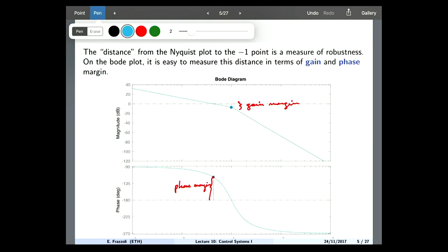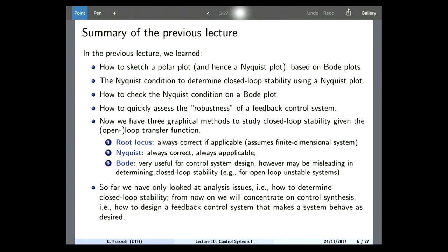So essentially what happens is that I'm shifting this whole curve up, which means that at some point your gain margin will be 0, right? And then you encircle the -1 point, meaning you're being too aggressive with your control, you're making K too large, and your closed loop system will be unstable. So forget about steady state error. You will not have a steady state because the thing is exploding, okay? So these are some of the issues that will arise.